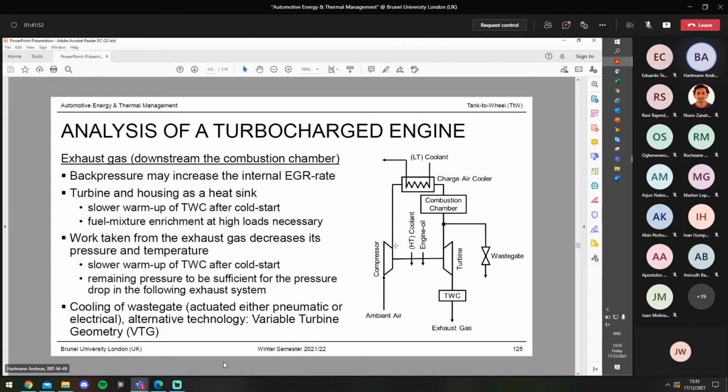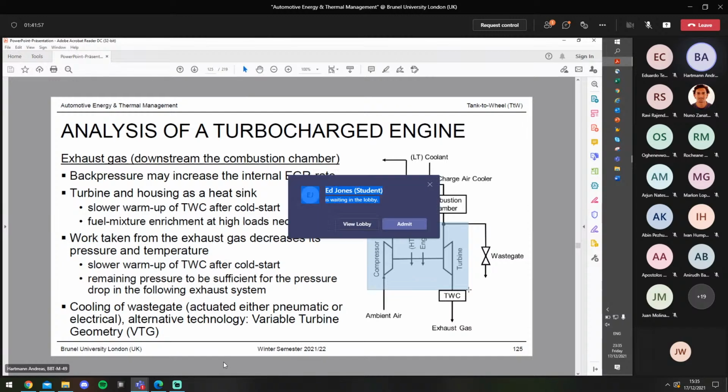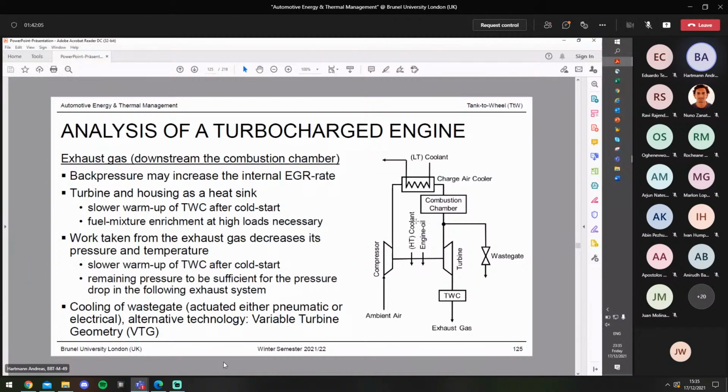Okay, yeah, that's right. So on the one hand, the turbocharger itself, especially the turbocharger of gasoline engines, might be cooled by a coolant. So therefore, you put more heat into the coolant itself. But if the power of the combustion itself is increased, for sure you also create more waste heat in the cylinder head, and therefore the coolant must be more powerful in this respect as well.